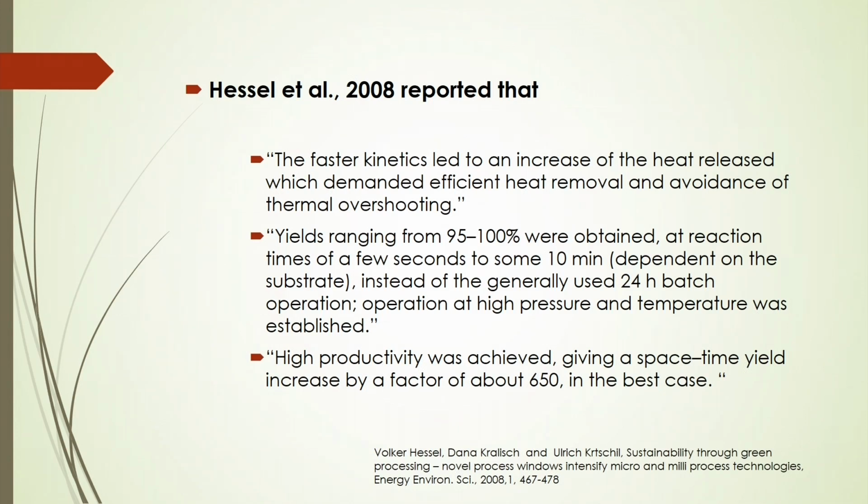You can also say that operation at high pressure and high temperature can be established based on these microchannel based reactors, and high productivity can be achieved, giving a space time yield increased by a factor of about 650 in the best case, as per Hessel et al.